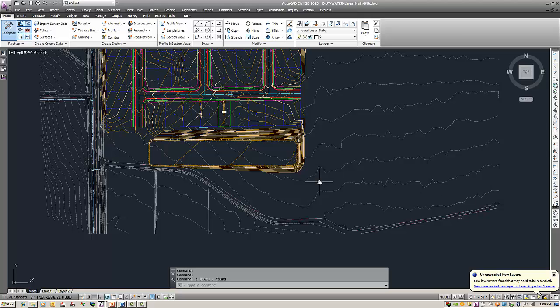Before we go and do this, I would like to bring your attention to the polar tracking options. What we want to do is, our parts that we're going to be utilizing are what? Bends of 11 degrees, 22 and a half, 45, 90, and so on. So it'd probably be in our best interest to lay them out in that fashion. Now, I've seen in the past where people have developed very cool dynamic blocks to be able to do that. However, I think we're sometimes missing the generic ones that are kind of right there for us.